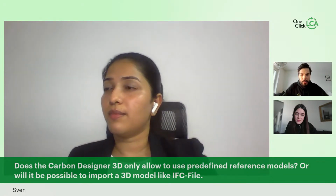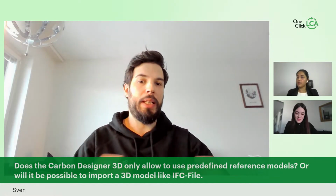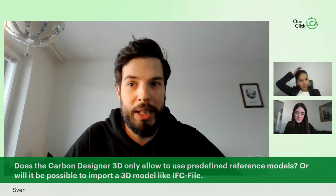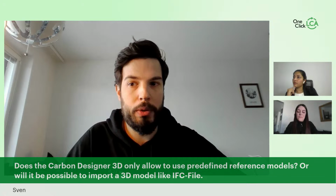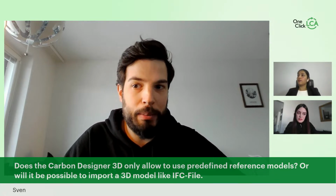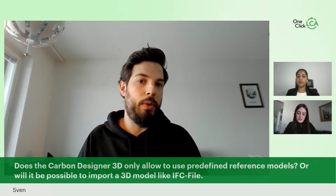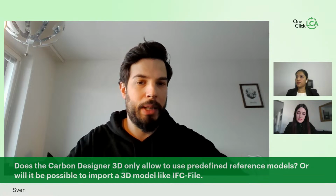Right. So Carbon Designer 3D has the predefined reference models out of the box, but then one can use the feature we refer to as private templates. So you can create a template that is made out of your custom solutions that you think are more appropriate for your case. And then you can use these alternative templates and generate typical buildings based on them. So template content can be, for example, a specific wall you do for school buildings, and external walls, internal walls, and building floors, for example.